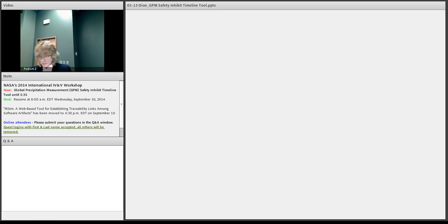Basically, hazard reports are provided to the range to describe what can cause a hazard, control a hazard, and verify controls of a hazard. Special additional verifications were added to the GPM hazard reports that were only required because we had safety critical software, those X's you saw on the chart. So I'm just going to hit the highlights here. Basically, we made sure that for our safety critical software, no more than one safety critical command in an onboard script, or RTS, could be sent at one time. Only one inhibit could be removed for each ground command. So we had 3 separate ground commands for 3 separate inhibits.